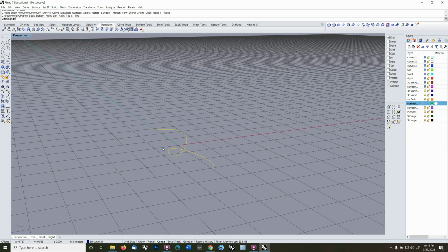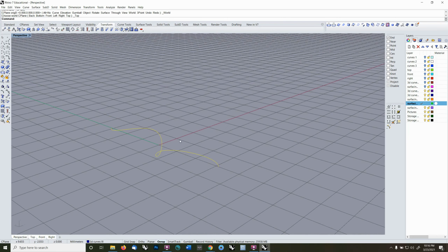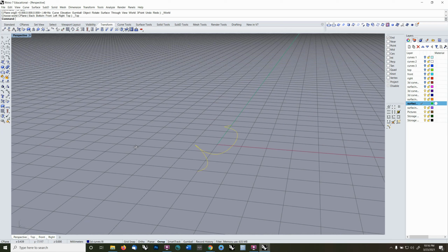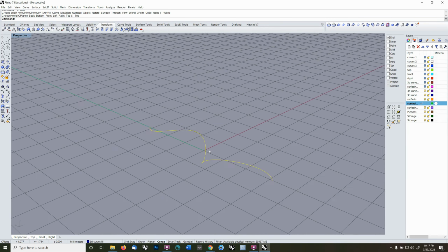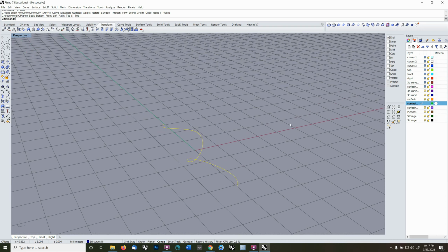You're always drawing two-dimensional. You can edit them into three-dimensional curves, which I just did, or you can use Rhino commands, like curve from two views or projections or pulling to get these three-dimensional curves, or blend curves will also give you options for three-dimensional curvature. But now I've edited this into a three-dimensional curve, we will do that same experiment with the extrusions.